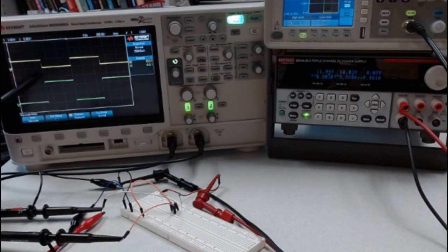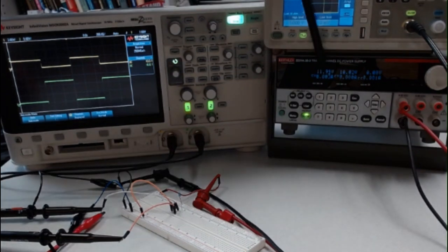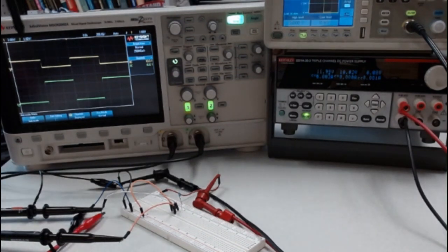But look at the voltage. This one is 2 volts per division, and this one is 5 volts per division, and it goes a little over 2 divisions, so it's about 12 volts. That pretty well matches our 12 volt supply, which is set up over here as 12 volts. So basically what we've done is we've amplified a signal and we've switched it. 2 volts on, 12 volts off. So we've actually created a switching circuit.